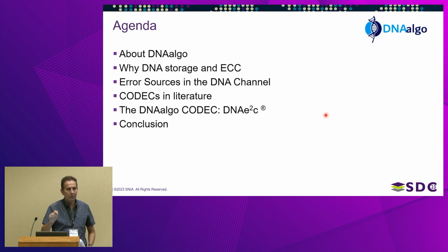Unlike telecommunication channels and storage channels, the channels in DNA storage are very diverse, very wide-ranging. So when I talk about the standard codes like Reed-Solomon, LDPC, those were developed historically by mathematicians, but they were applied to channels that had pretty much a range that we understood, like copper, or like NAND flash that they were showing, or disk and tape. The channel distribution is somewhat known.